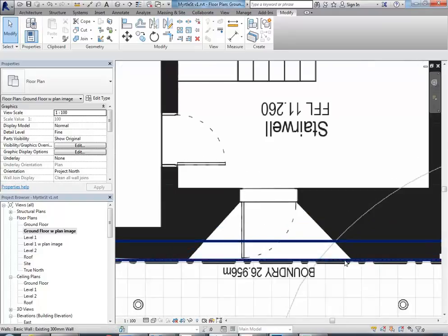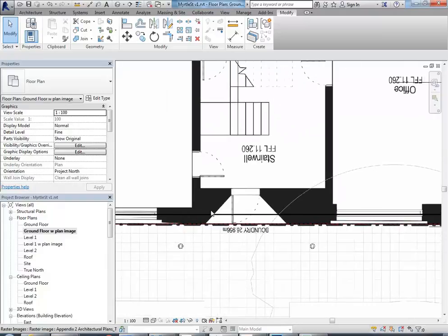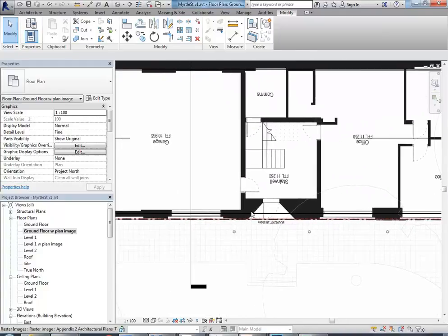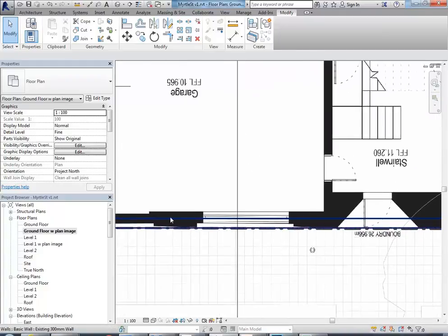Okay, so this recess section here, that's an interesting one. There are a few ways of doing that. I think for this, maybe you could just use more walls. So have walls coming back at an angle and then across, and see if you can join them together. The, I suppose, technically correct way to do it is to put a void in and cut away that angled section. And you can do that. So maybe later on, if we get time, we can have a look at that. But for now, I'll just try and keep it simple and do it with wall thicknesses.